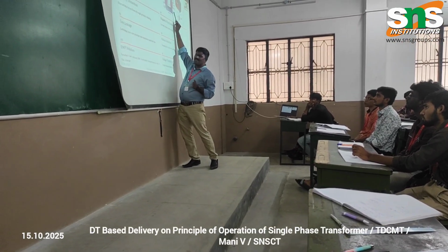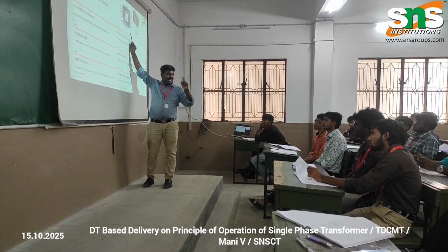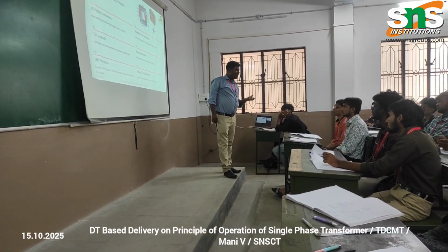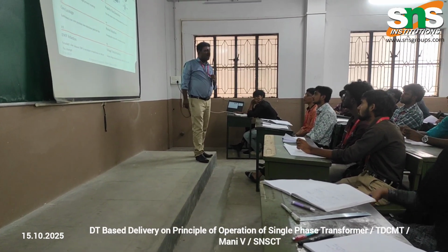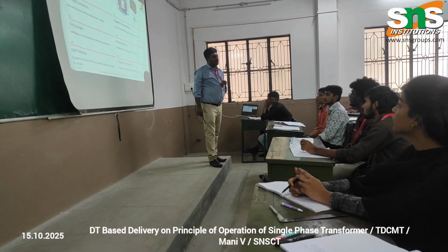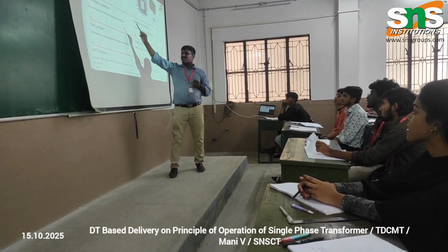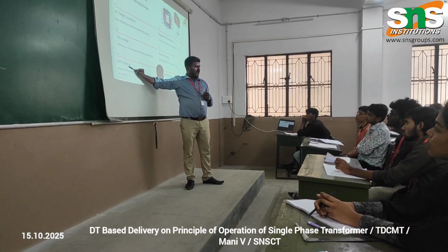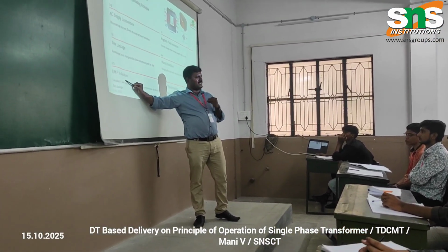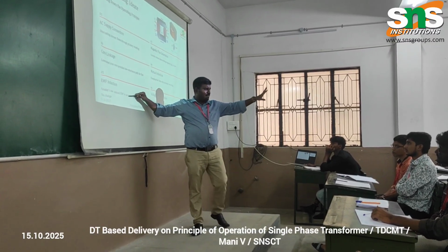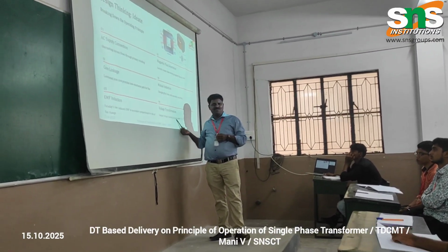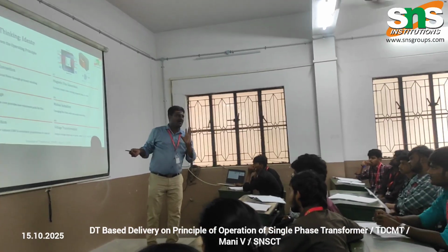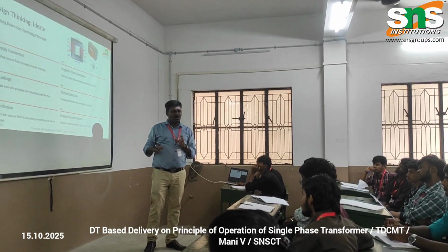When the flux is linking with the secondary winding, at that time what will happen? What will happen in the secondary winding? Mutual induction. According to the mutual induction, the EMF is induced in the secondary winding. With the help of the mutual induction principle, the EMF will be induced. Then the induced EMF, the induced voltage, will be taken to some loads. According to the load, we can vary the output voltage by adjusting the number of turns.